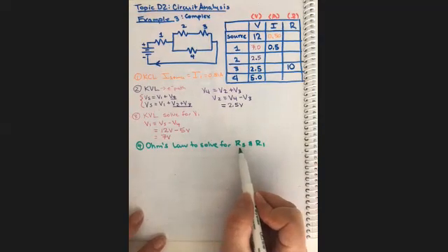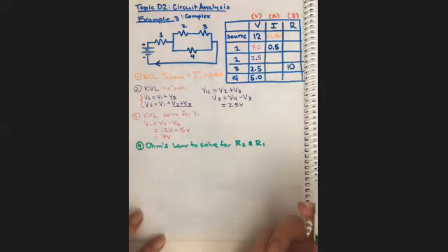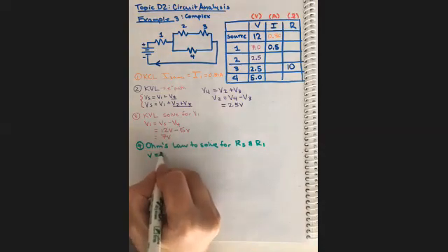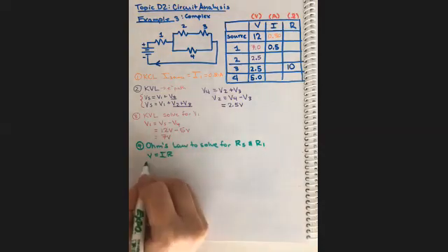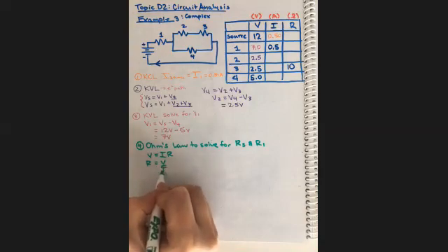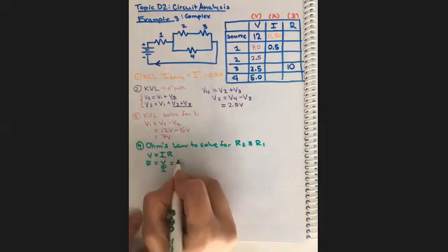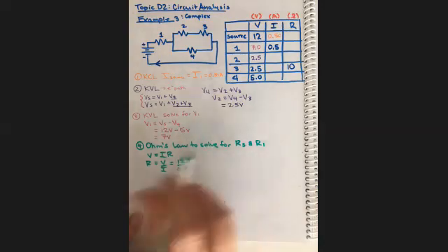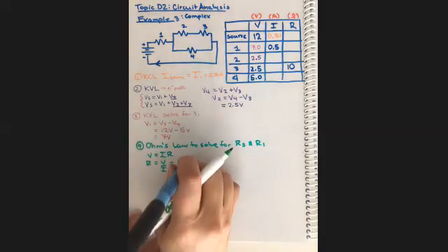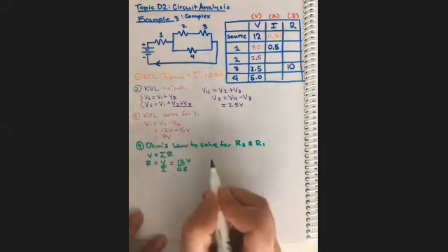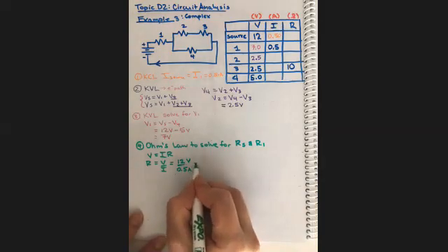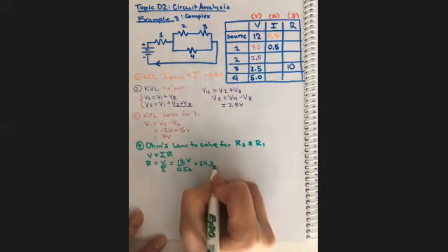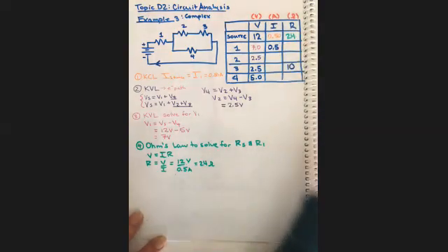There's no resistance through the battery. The battery is the opposite of resistance because you gain voltage. But anyways, I think you know what I mean. R total, you can call it. So if V equals IR, R is equal to V over I, which is equal to 12 volts over 0.5 amps, which is 24 ohms. So we've got 24 ohms.